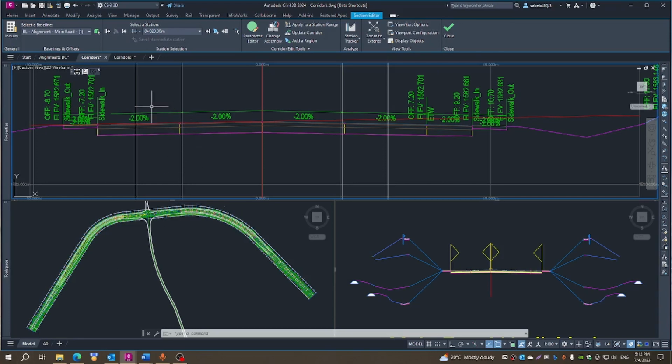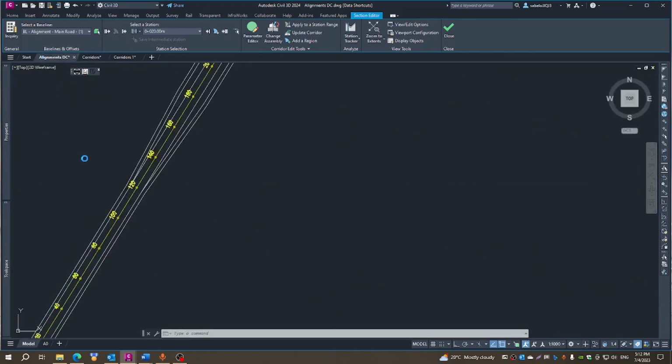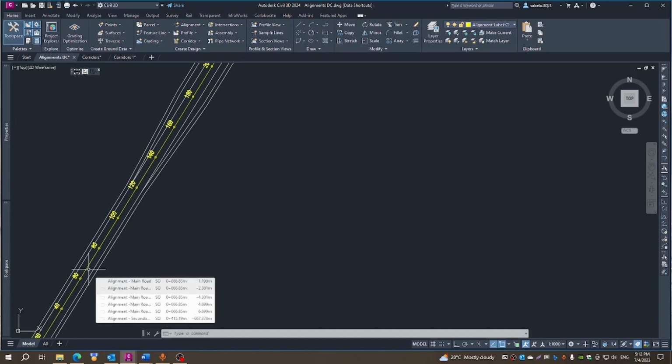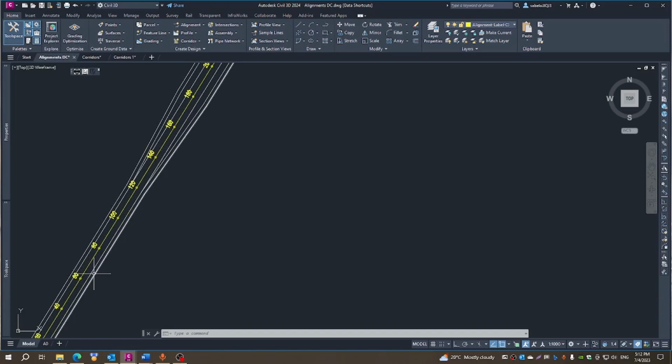So we will be using targets to control the width of the road in this area where we do not have the median as yet. Again, just to refresh our memory, this is the area we are dealing with, and as you can see here, we've got a single lane and a single lane, and we've got a shoulder on each side of the road. But as we get to this point, there's the road center line. We don't have a median yet. We've got a lane, then we've got a shoulder. So there are two lanes on each side, but at this point it's only one lane each.